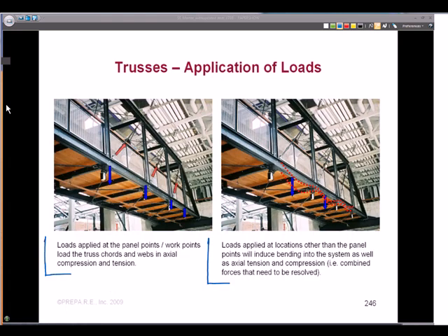Okay, so this footbridge, if we look at it, has all the various components of the load path. Think about these beams supporting the floors and the people walking on this system. And they get their load to the system by spanning this way. So why are there beams in between the panel points? Why can't we just load it at the panel point or at this vertical? This is where we want the loads to come in, to be injected into the truss. So why the extra beam?